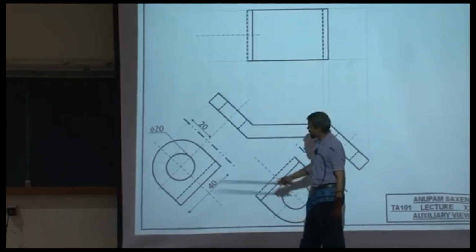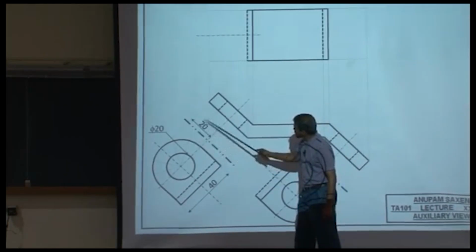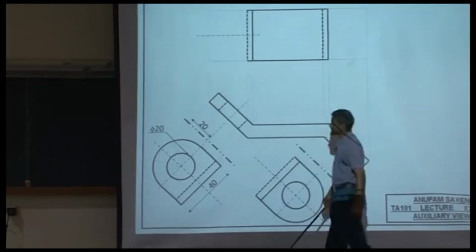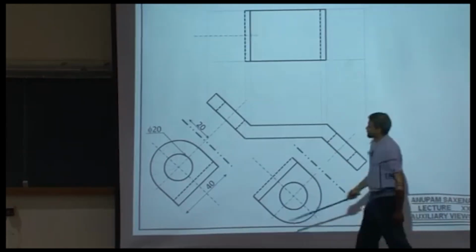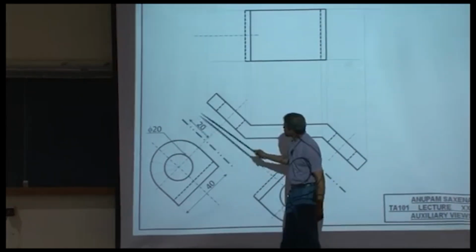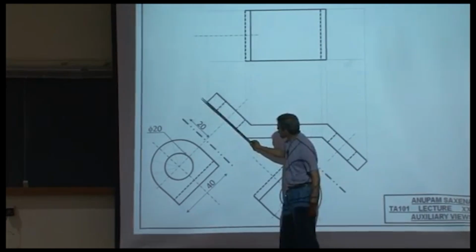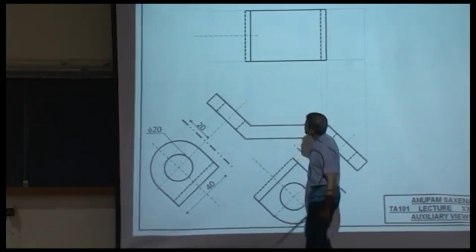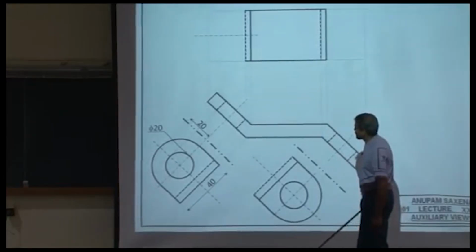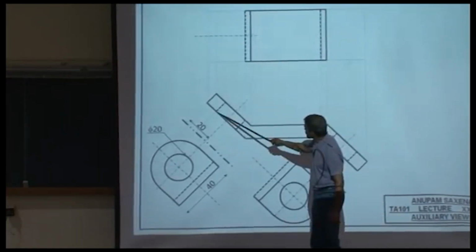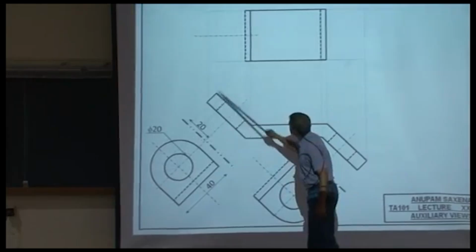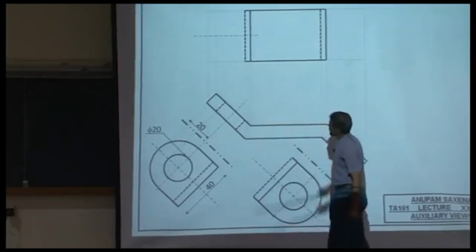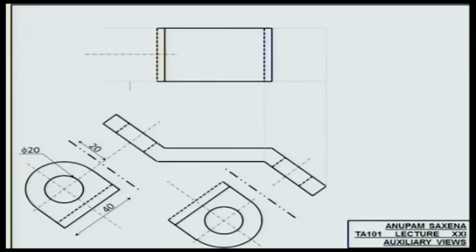Then look at these projections, transfer these projections over here, and from here up to the top view. So these 2 points get transferred over here. Let's first look at the bottom face. From here, transfer them up, right there. Second thing, transfer these 2 points over there. Likewise, the center line up there.